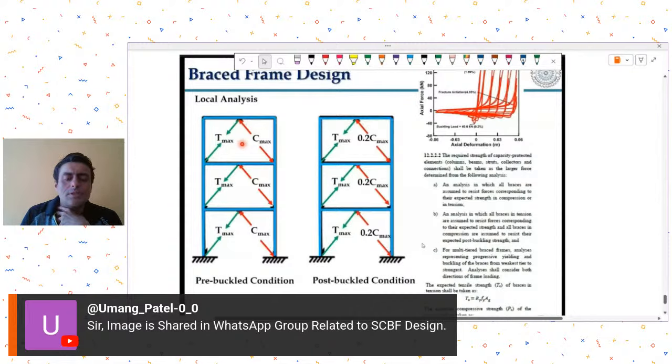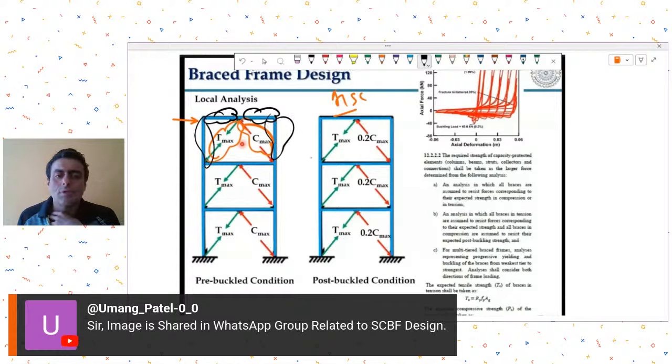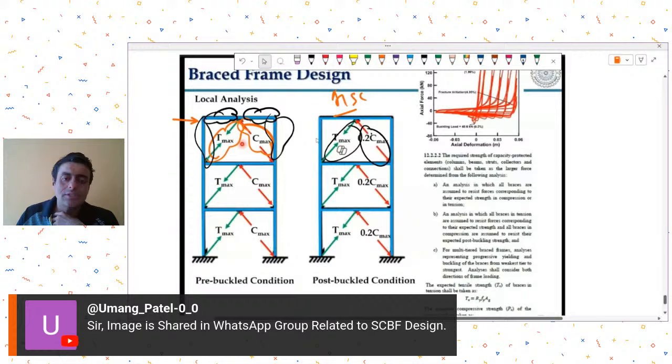I'm not sure about it because what I had seen in some of the AISC documentations, they had not done it this way. They had just applied or ensured a force to be applied in a manner in which the bracings get to their required tension or compression forces, and then they take the corresponding forces in beams and columns, and design it accordingly. So I'm not sure about this. If the member has to be removed and then you apply nodal forces, I'm not sure.